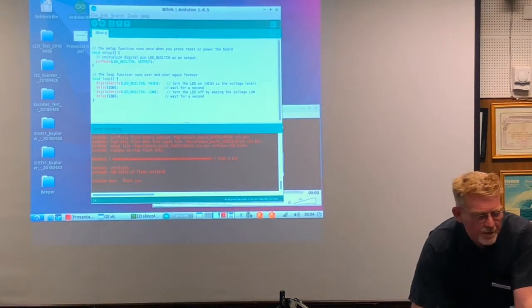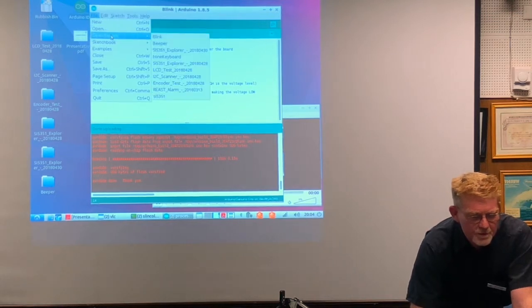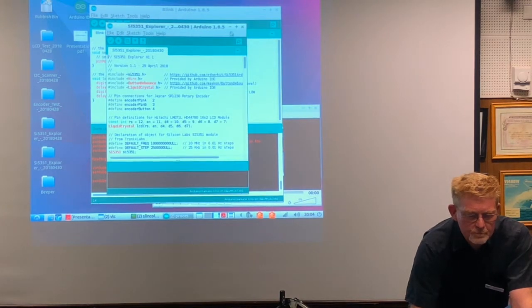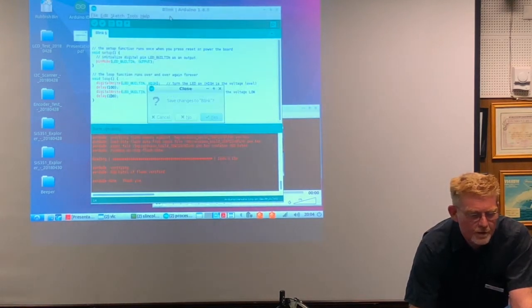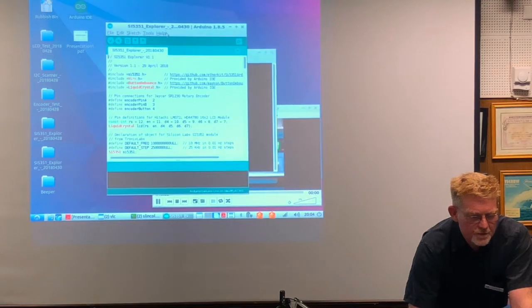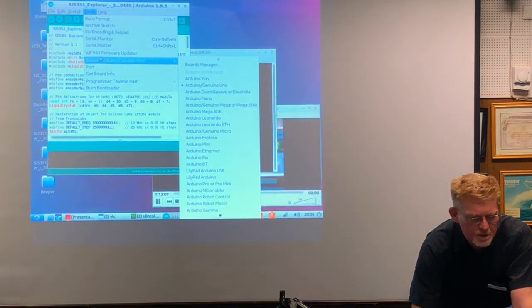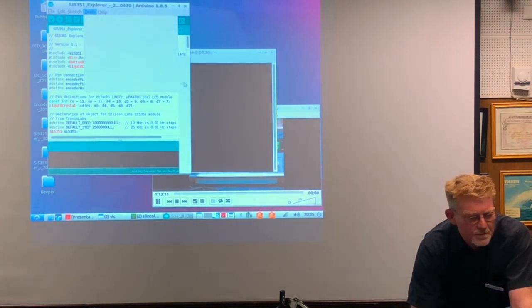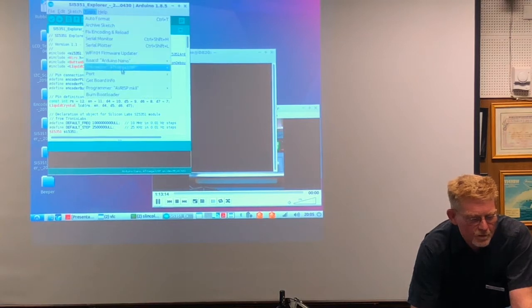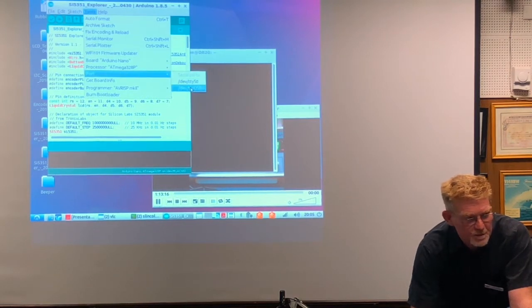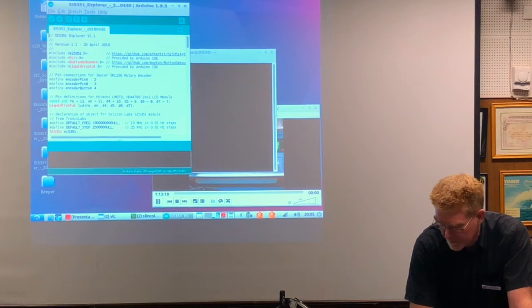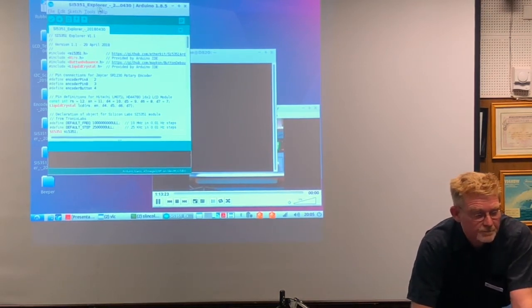And if I go back here and find the recent script sketches, it was that one. So let's get rid of that. No, I don't want to save the example. Now this is a different device to the one I showed you before. This is an Arduino Nano. So we tell the Arduino environment what it is, and then I tell it what port it's on, and that's actually on USB 0, because the USB converter chip is different to the one on the classic Arduino.